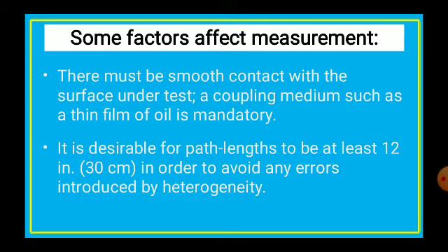There are some factors that affect measurement. Kaya ito yung kailangan na binabantayan din in using or in measuring, testing the concrete specimen. So there must be smooth contact with the surface under test. A coupling medium such as a thin film of oil is mandatory.